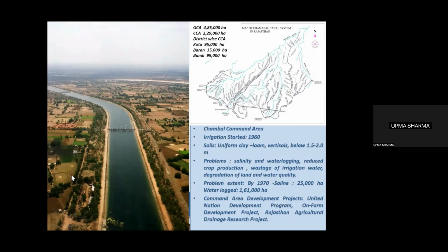as a joint venture between the central and state government and the Canadian International Development Agency, the Canadian government. The main aim of this project was to implement a large scale of horizontal subsurface drainage systems and related water management techniques to control irrigation induced soil salinity and waterlogging. The area selected was 53 hectares, and it was implemented on areas which were already treated by the on-farm development programs.